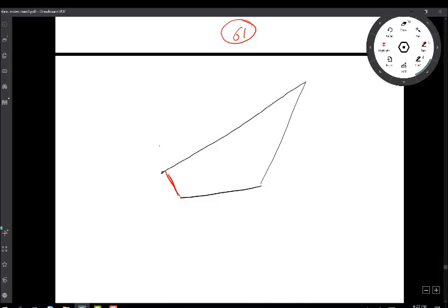Then link number 3, and here is ground. So this is link number 2, so I put 2 with a circle. Link number 3, 3 with a circle, 4 with a circle, and 1 with a circle around it, and then I find my points. This point is common between 1 and 2, so I put 1,2 on it, and this is 1,4.